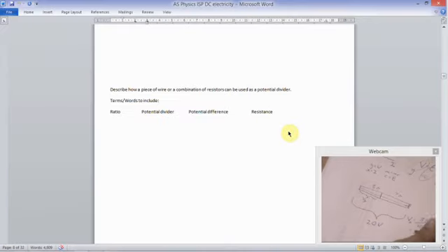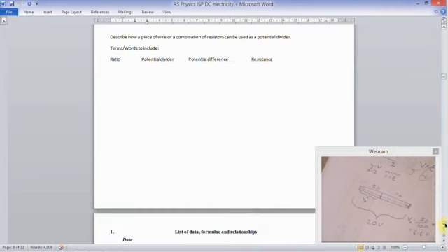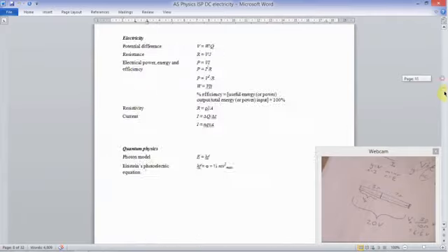6.6 recurring volts. So the rest must be made up by this part over here, which is 13.3 recurring. So that's how this idea of potential dividers works. So the ratio of voltages is the same as the ratio of resistances. I've been through some simple ways of doing that in class with you guys. So let's get stuck straight into our questions.